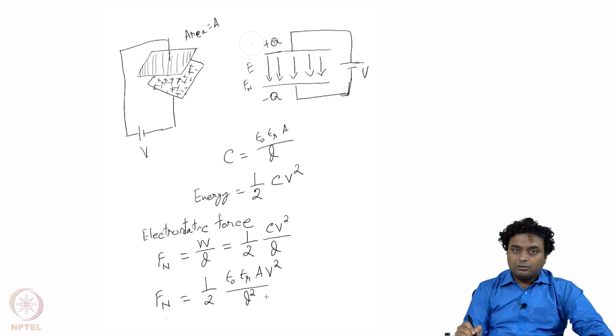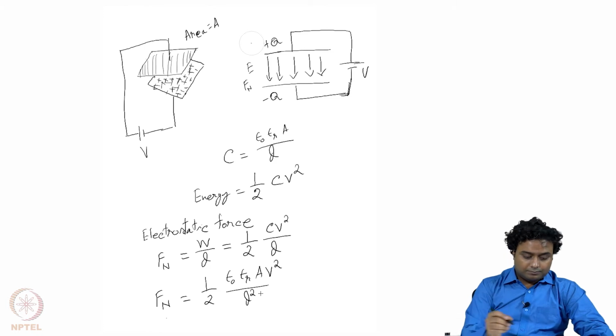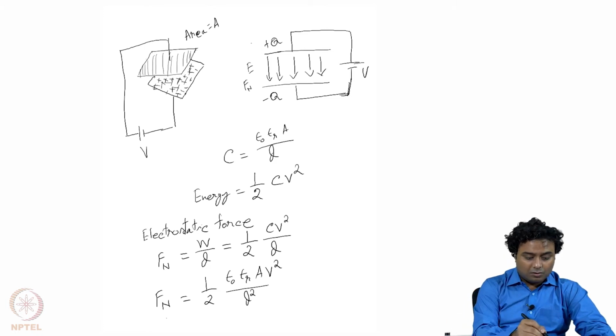But as we do miniaturization, then this D can become smaller and smaller. So if we have two plates in separation of, let us say, a few nanometers, then in that case I am getting a 10 to the power minus 9 at the bottom, okay. That 10 to the power minus 9 takes care of that epsilon naught, and because of that the force can actually be very high. So we will see that with some example later on. So now this is the normal force.